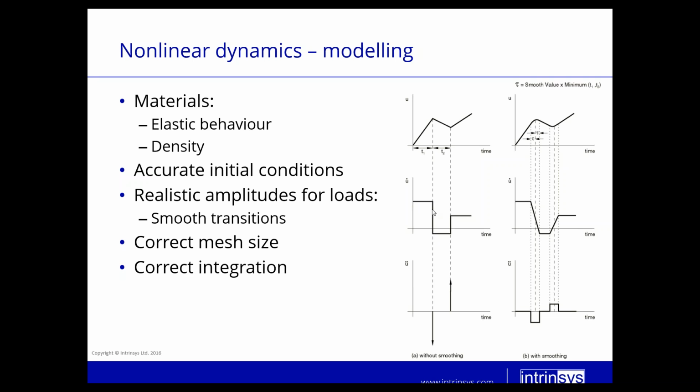And if there's a step change in the speed, that means we have, well, either infinite or at least very high accelerations. And all these very high accelerations would generate shock waves into your part, which is not good because these are not present in reality. These are only present because you defined a kinked displacement curve. So how to get around this?